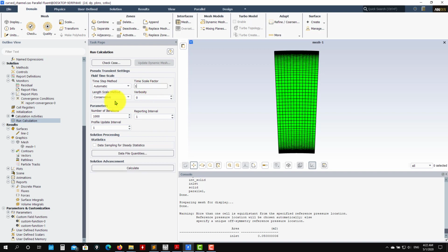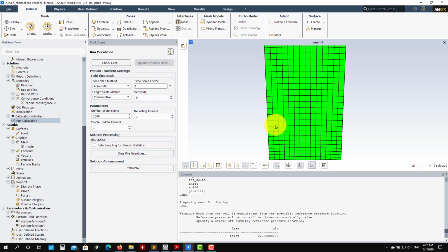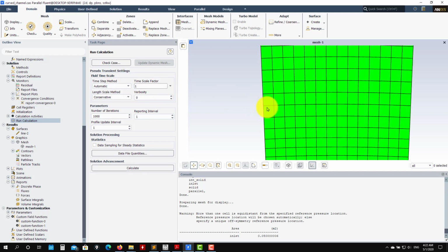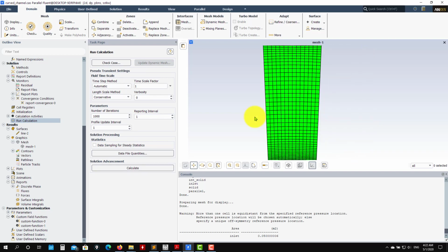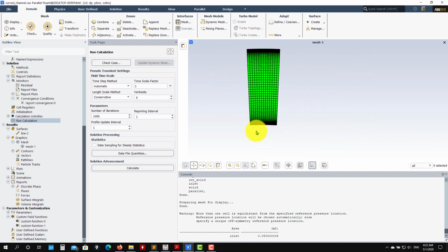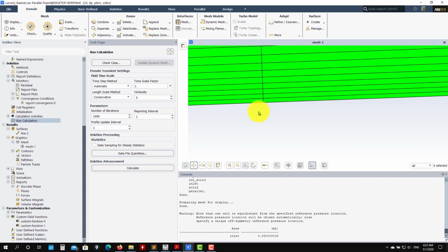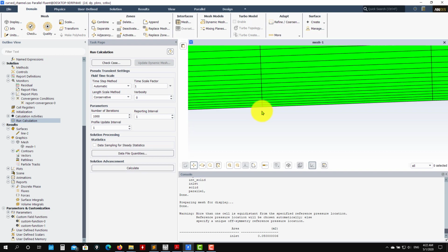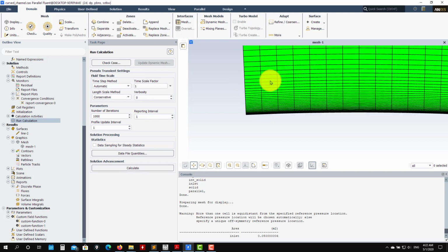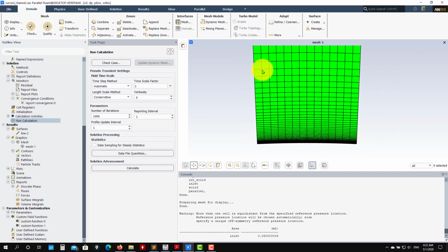See that by default here you have 1, and I'm going to show you something here that this controls. This is pseudo transient, so here you have somehow the time entering your computation. What it is doing is that each cell has a different time step. When you have fully unsteady, it is a global time step, so the smallest cell is the one that is going to control your simulation with the CFL number. When you do pseudo transient, each cell will have different CFL numbers.